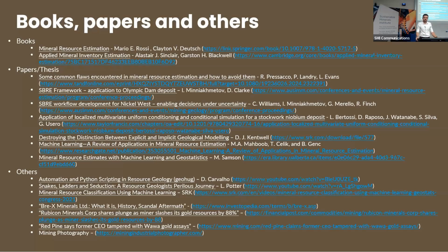Another question, from Sheila: could you explain more about the link between the environmental risk assessment and the resource modeling? Yes, it is a little bit classified, but what we can do, for example, is this. Let's say you have possible acid-forming material, right? Then you know exactly which portion of your deposit will have that PAF material. So you can use the resource modeling and the probabilistic resource modeling to generate different scenarios to understand, okay, this is probably the average tonnage that we'll get of that PAF material, but you also have a range. With that range, you can plan ahead on the footprint of the waste dump that you're going to use for that PAF material, right? So that has a direct impact on the planning of the waste dump, for example.